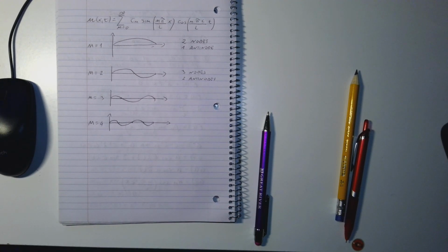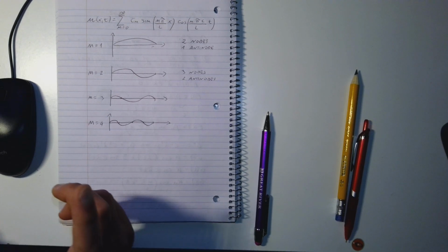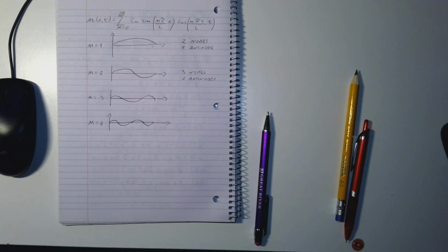At the first mode you typically have the higher amplitude, and at the second mode a smaller amplitude. So in general, for structural analysis, you don't want to get close to the first mode of vibration, because it gives you the highest amplitude. You always want to stay very far away from it.